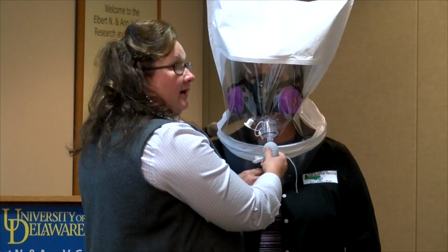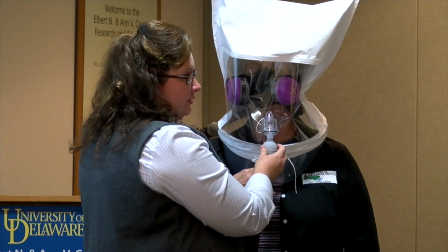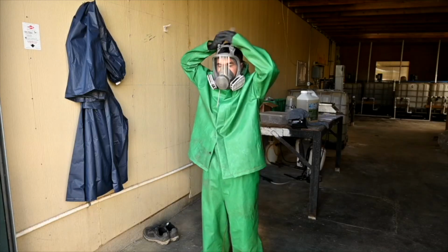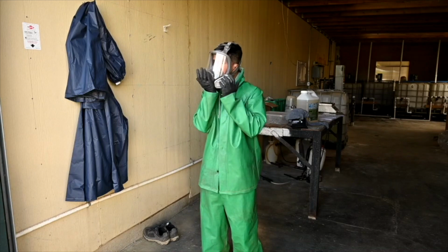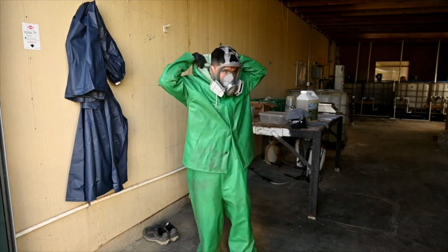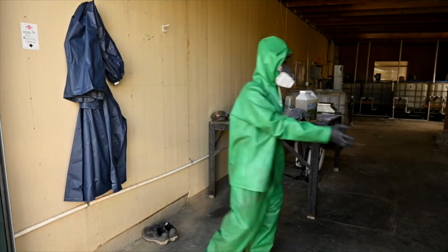If you cannot achieve a proper seal due to air leakage, you may need to be fit tested for a different respirator model or size. A user seal check should be completed each time the respirator is donned or put on. It is only applicable when a respirator has already been successfully fit tested on the individual.